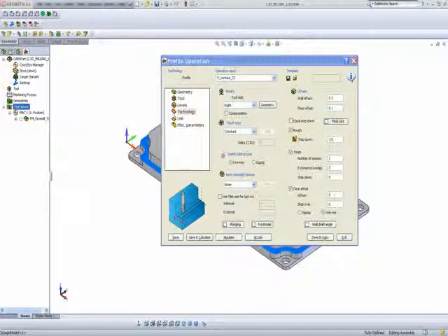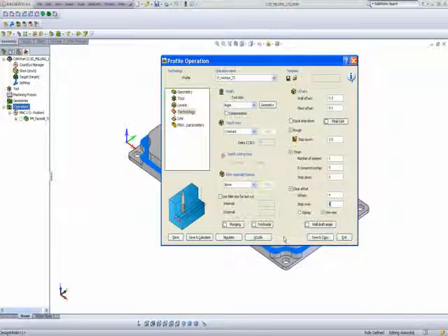Now I'll choose my clear offset as being 4 millimeters. In other words, my first cut to be 4 millimeters away from the wall itself. And then my step over, how much should I go in every single time? I'll go in every 2 millimeters.